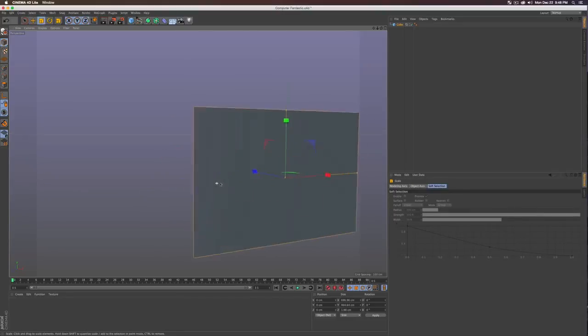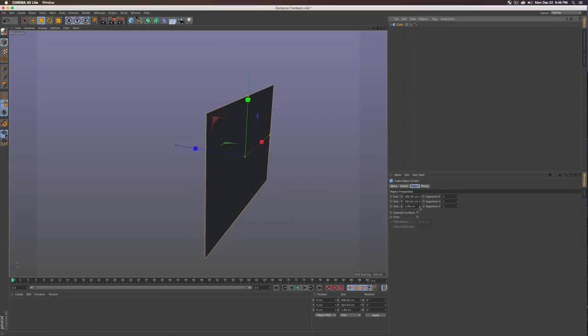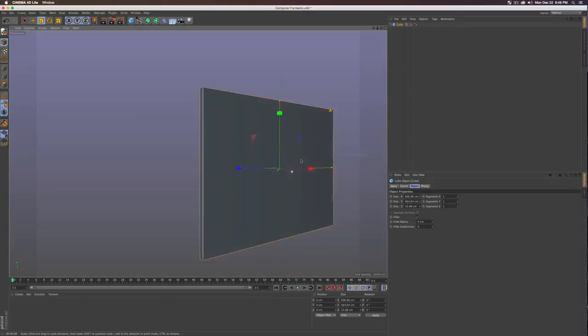It really doesn't matter too much what everything is looking like. And then I'm going to turn the Z size up a little bit, add a little fillet, whatever the heck you want to pronounce that word as, on the edges here, and maybe turn the radius down to 4, and the divisions I'll turn up to 6. And wow, look at that, we have a wonderful start of a computer monitor. So that is the first step.